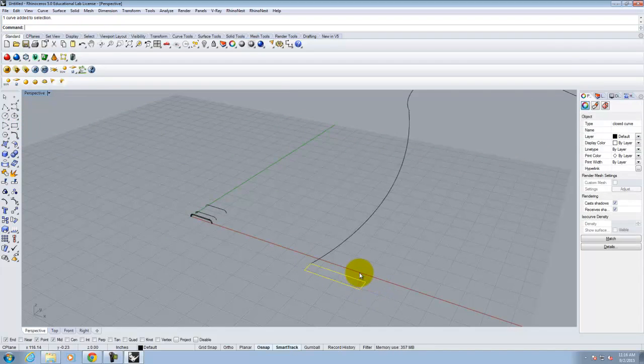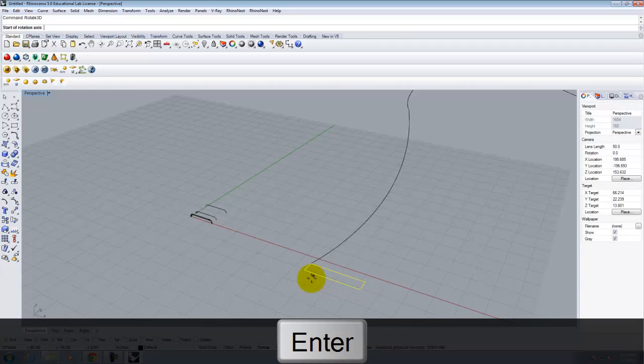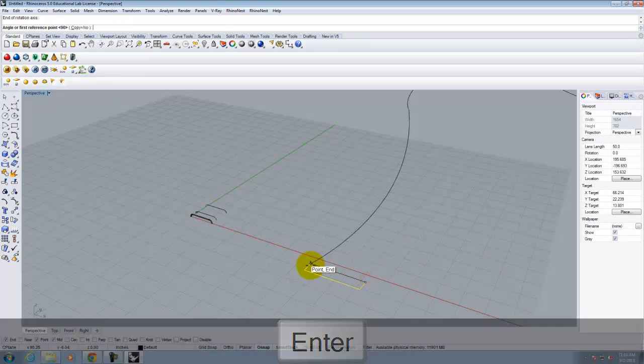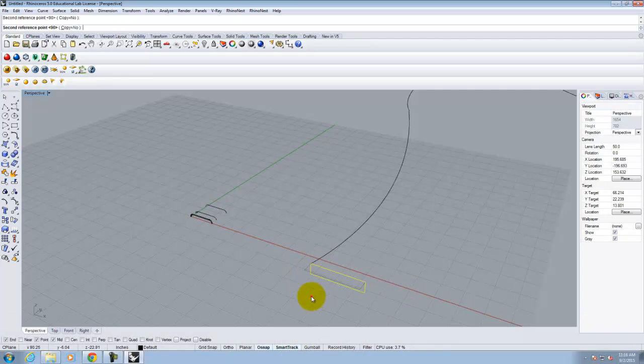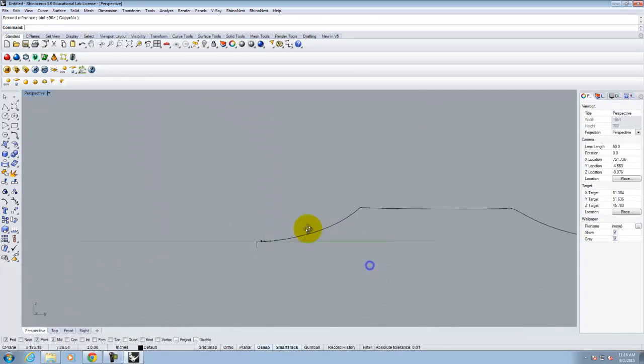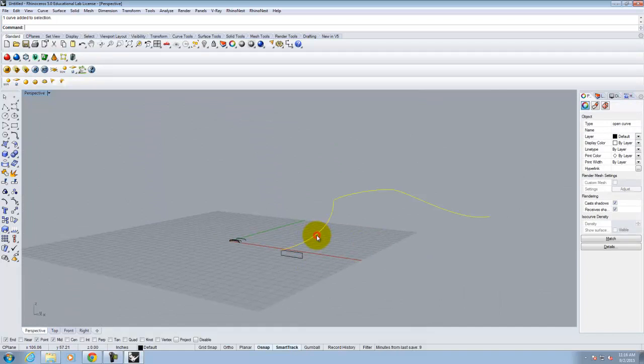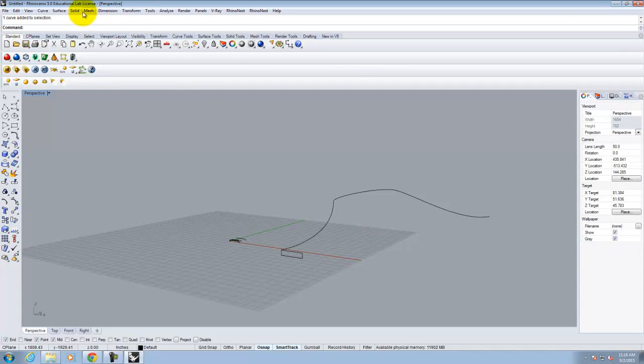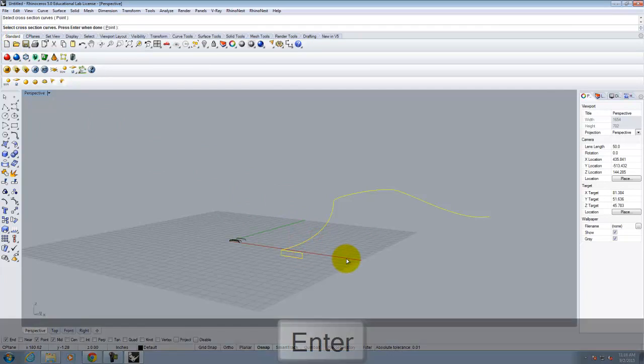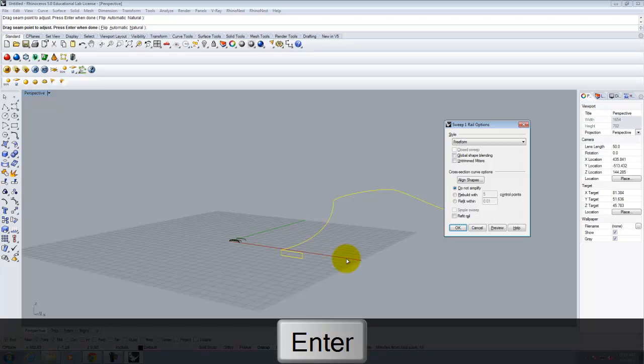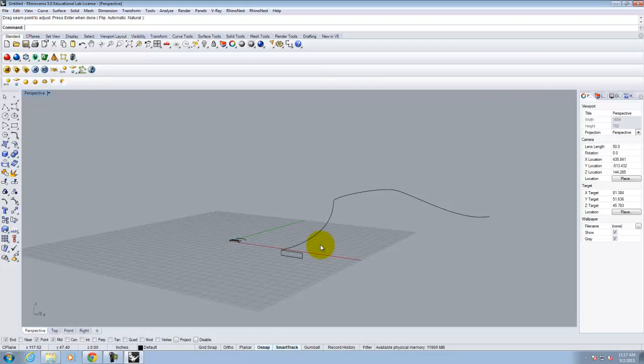And then I'm going to rotate 3D so that this is then down in cross-section, something like that. Okay? So I can then use this as my rail and this as my object, and I can build this. Basically, I'm building kind of a ramp. So let's go to sweep 1. Rail first, cross-section curve next. Enter. There's my seam. Let's go ahead and I'll say OK.